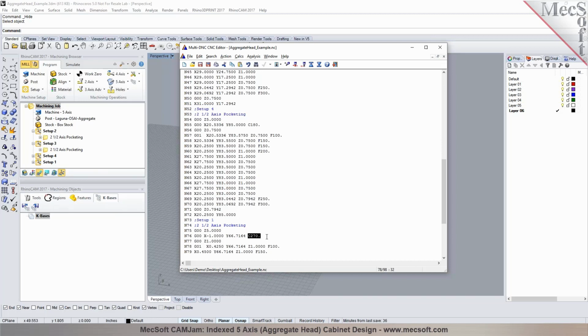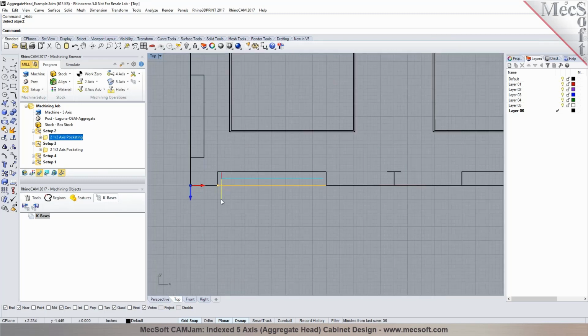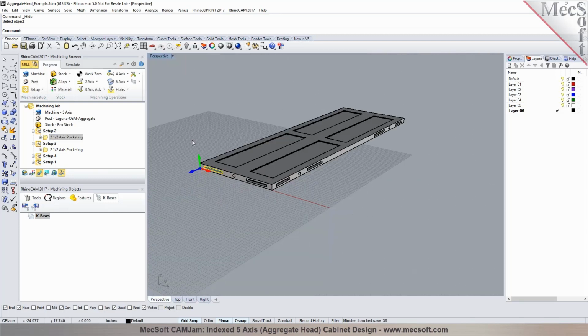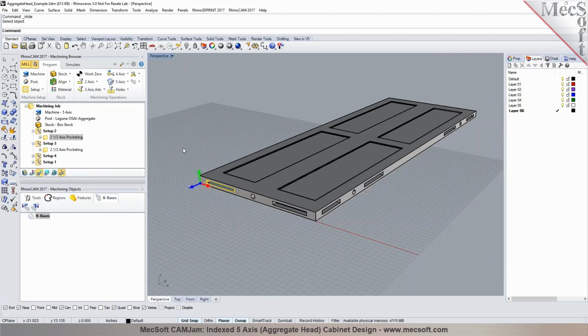After the axis is rotated, it takes care of the transformation of your coordinate system in here. So for example, when you're processing the toolpath on this front side, technically you're moving the cutter in and out in the Z-axis, but when you look at it at the machine, it's the Y-axis that's moving in and out, right? So our CAM system takes care of all the transformations back to the world coordinate system. So that's all taken care of in the CAM programming. The user does not need to do any additional transformations. So everything is computed.